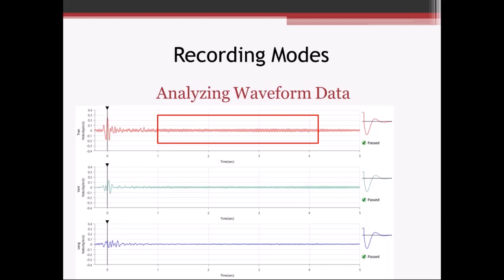This is some kind of sustained event, because it's at least lasting more than 5 seconds. It continues beyond the initial event that triggered it at 0.25 inches per second. This was vibratory sheet pile installation, by the way.